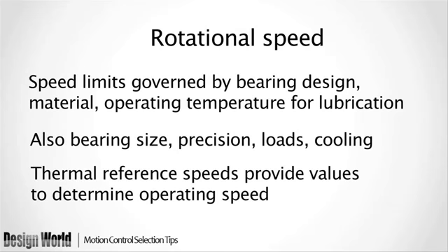Basic thermal reference speeds will provide designated values to determine the permissible operating speed of a bearing at some defined operating temperature, when subjected to specific loads and lubrication conditions. Bearings can potentially operate at speeds above the reference speed when bearing friction is reduced or when heat is removed.